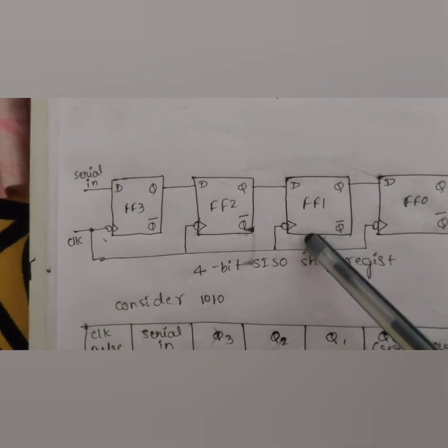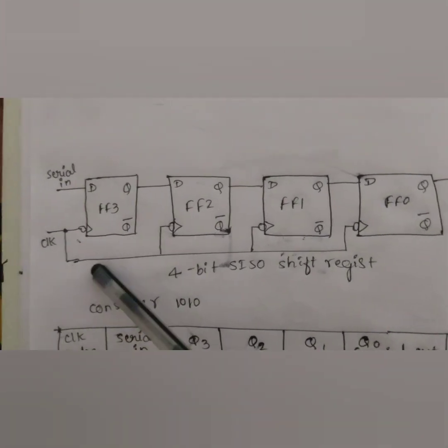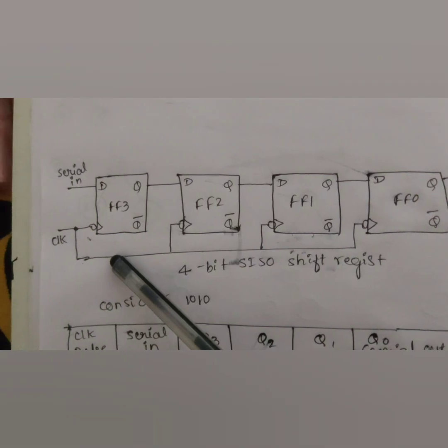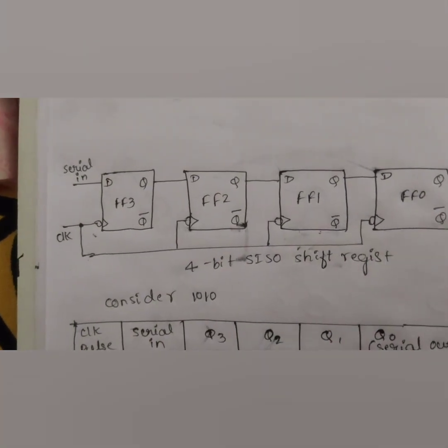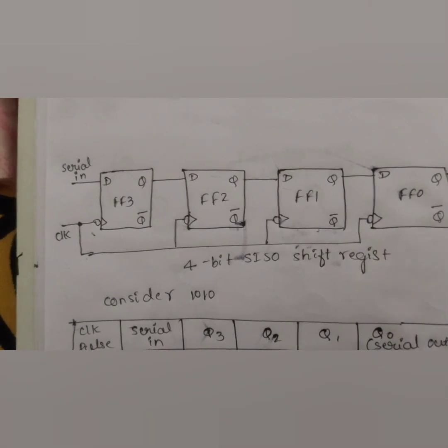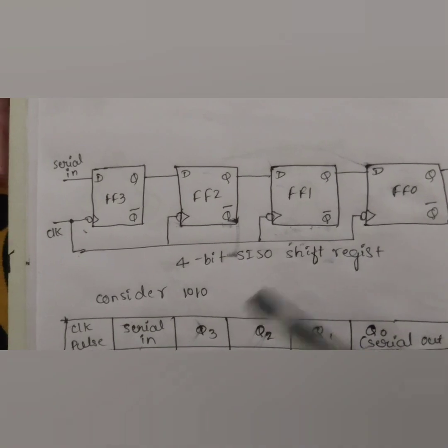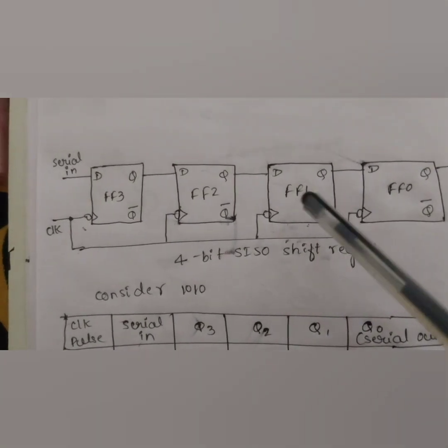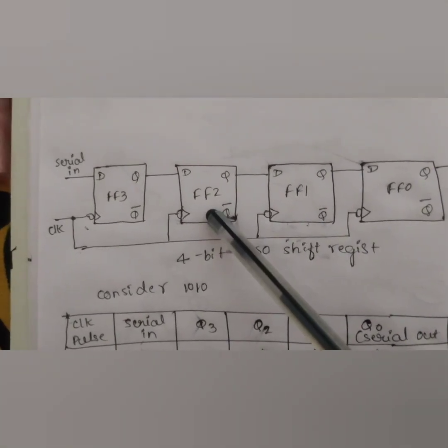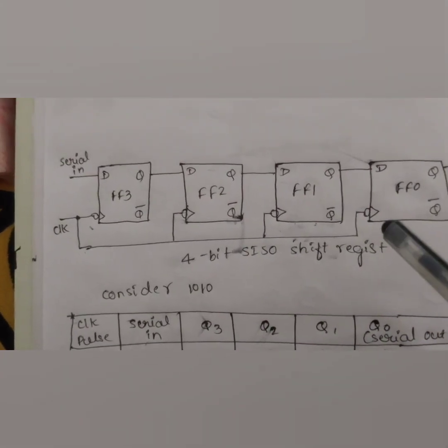In this shift register, bits can be sent serially to the input of the leftmost D flip-flop. Hence, this input is also called the serial input. For every negative edge of the clock pulse, the data shifts from one stage to the next. So, bits are received serially from the output of the rightmost D flip-flop. Hence, the output is called the serial output.